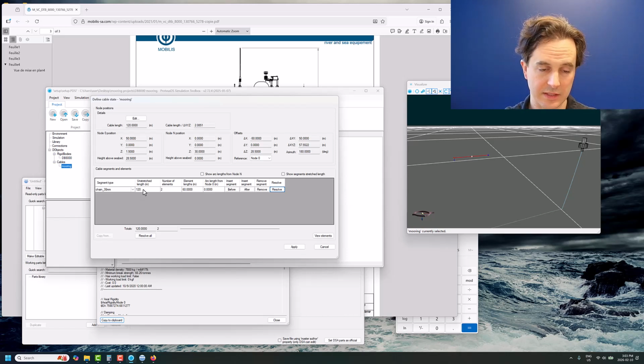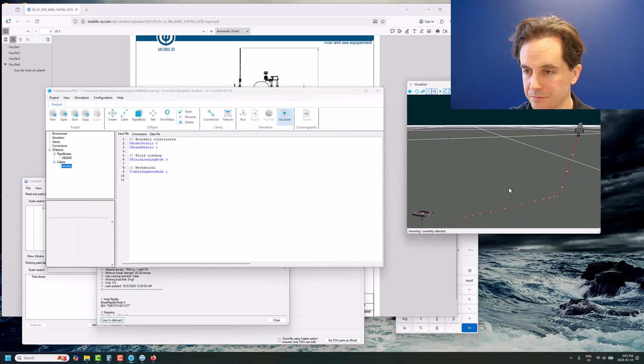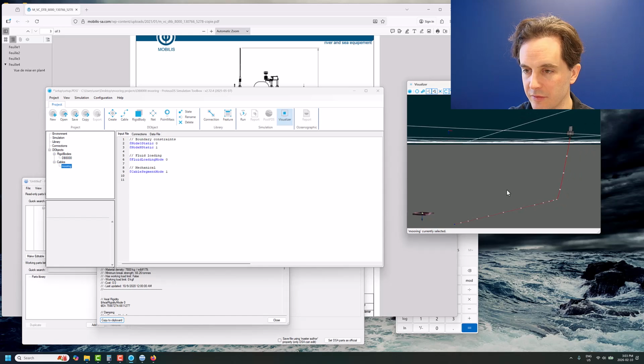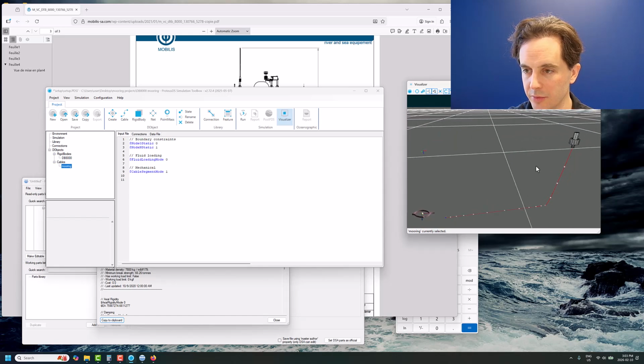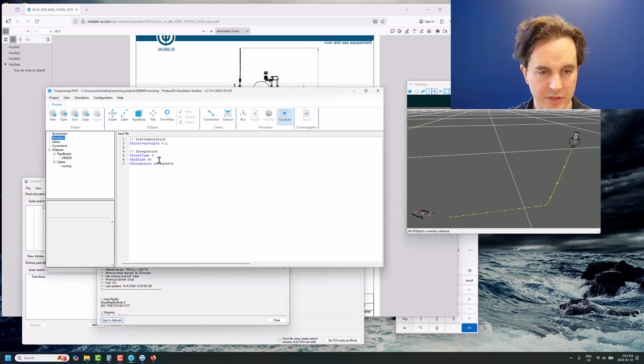And then you can see that it's automatically said, hey, you've got to add enough material here for all your elements. Number of elements, we should have quite a few more than 60 meter elements. It's pretty long. Aim for 8 to 15 meters for shallow water chain, but you can use your judgment and see what it looks like in the analysis. Then we'll go apply, and you can see we've got some information here set up for our buoy, and everything.